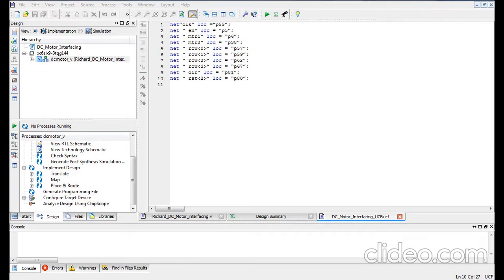Placement and routing is one such important parameter where we place components. We try and place those components which have a lot of connections very close, and those components which do not have many connections between them, we can place afar. So this is what happens in placement and routing, and this is a repetitive process, which means it keeps going on and on till it comes to an optimum design. So I'll be showing you in the upcoming sections how we implement design.